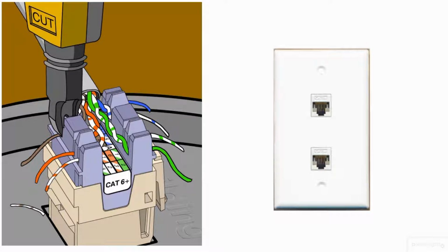There's a lot of human error that can take place here, though. Someone like me, I'm worthless doing this due to my color blindness. I have a fair amount of dexterity, but that's another problem. If the technician's not particularly dexterous, you can accidentally punch down 2 wires into the same terminal and create a miswire. You might have a wire that's not fully punched down, that's going to create an open, or you might have nicked a conductor that creates a short. You see, so there's a lot of human error, unfortunately, that can happen here.